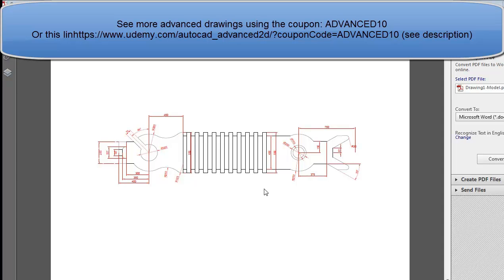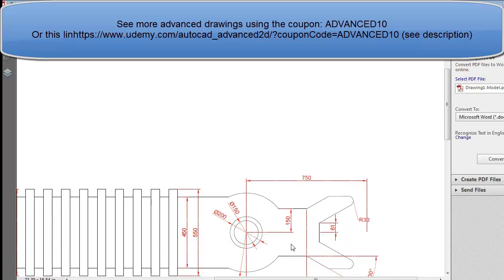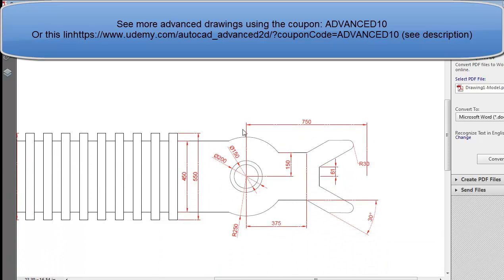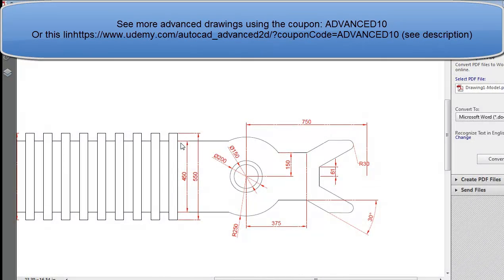So we need to draw this 2D object, and we need to search for a start point to start with. If we started with this point here, let me zoom in, we will see that we will draw all the shape to the right of this start point, but we have here this line from this point to this point that has an unspecified distance or length. So we will stop here and start again at a different start point.